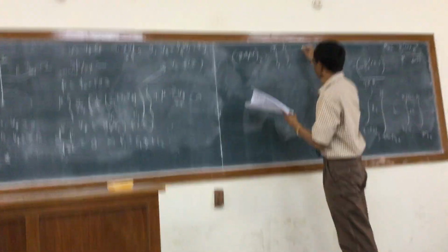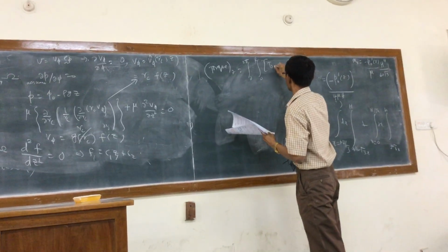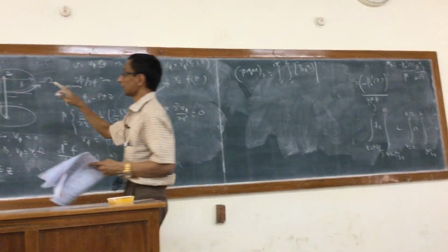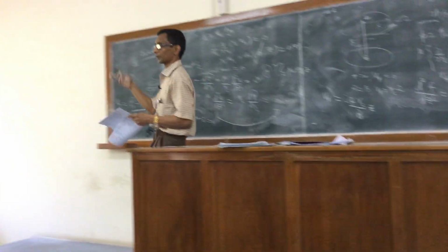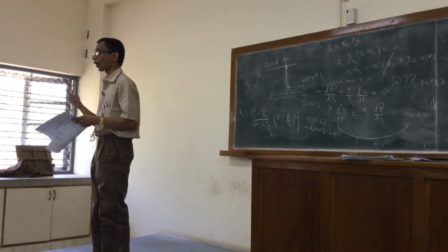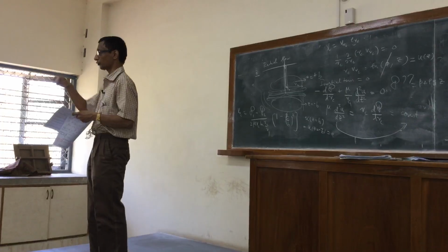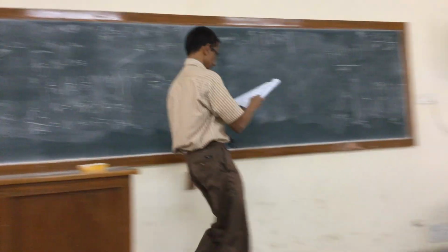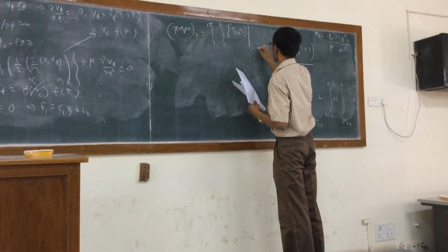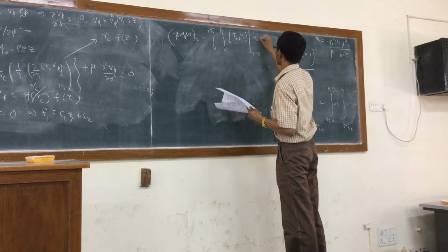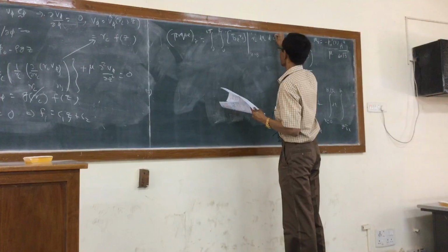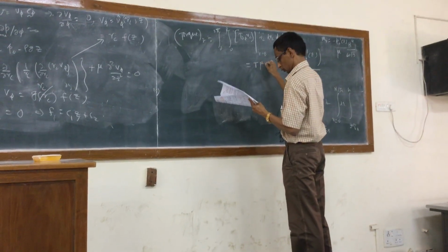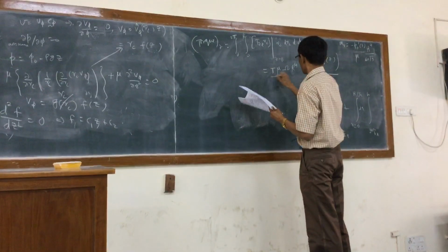What you should get is tau_z phi r_c. Everything is happening here at z equal to b, because that is where the fluid is in contact. That is the torque that is applied to the top plate to make the fluid rotate. Right? So this would be at z equal to b, and then we have the integral over r_c and phi, and you get this result pi mu omega r power 4 by 2b.